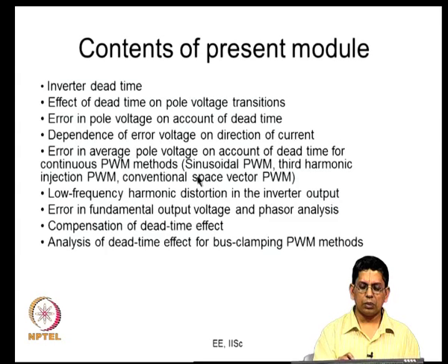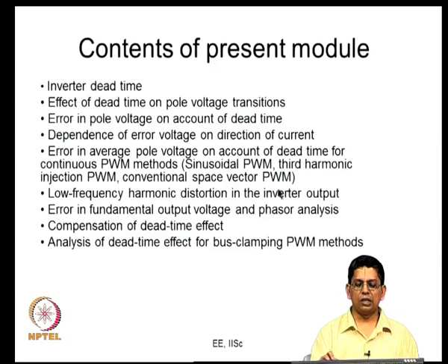But we would today, but after that we will look at sine triangle, third harmonic injection, conventional space vector PWM, etc., all these continuous PWM methods. We will essentially be showing that the dead time effect can be analyzed in a similar fashion for all these continuous PWM methods now.